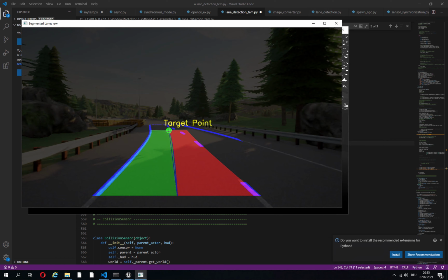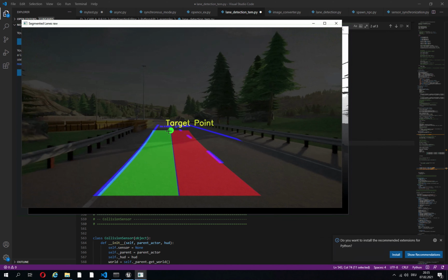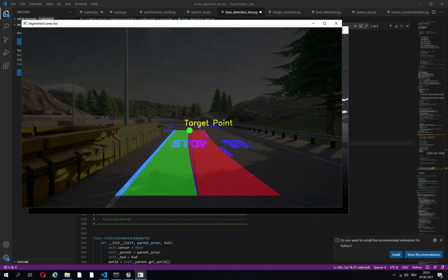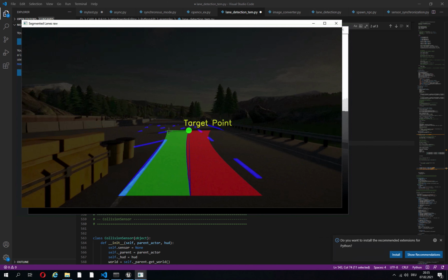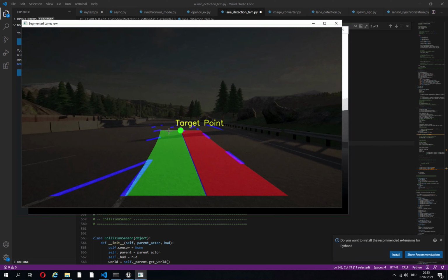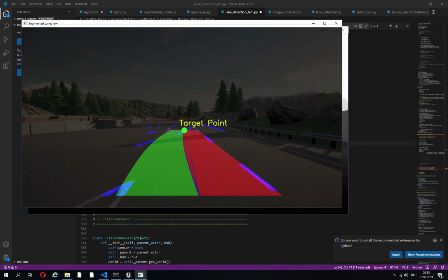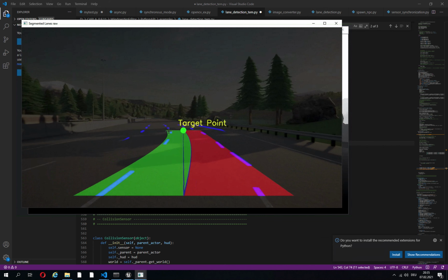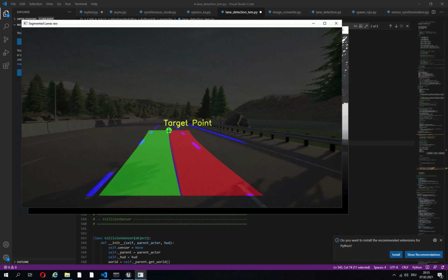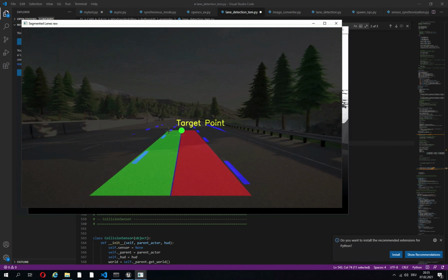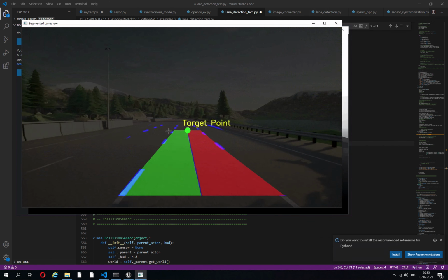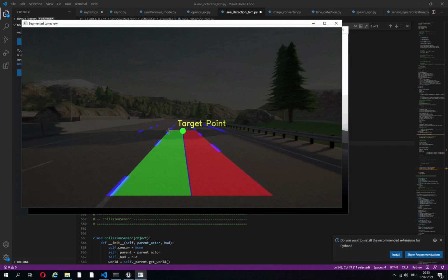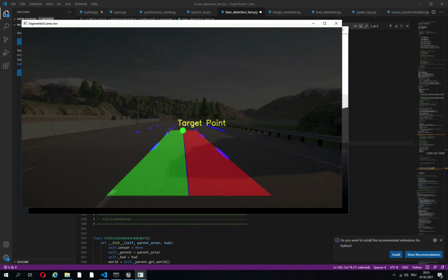And if I get the 3D location of that target point, I can use it as an input to the controllers. These controllers could be the pure pursuit controller, or just the PID controller that Carla used, that I explained in the second session, where the car needed to drive straight along the waypoints. It is exactly the same. We just need to give a different target point.